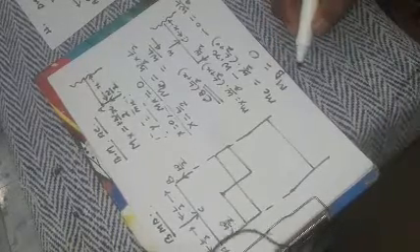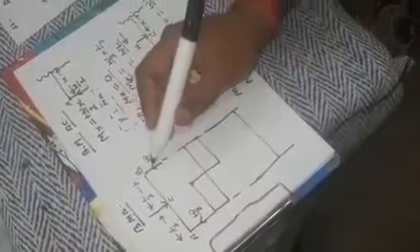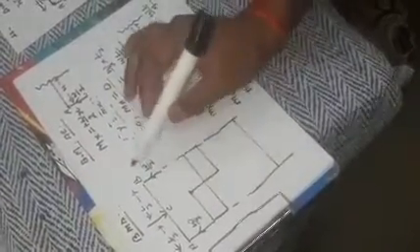So it is always a noted point that the bending moment at the start point of the beam, whether we are moving from left to right or right to left, when it is a load point, is always 0. In a particular case, when an external moment is given at a start point, then the bending moment is not 0. But whenever it is a load point, then the bending moment for the start points is always 0, right?